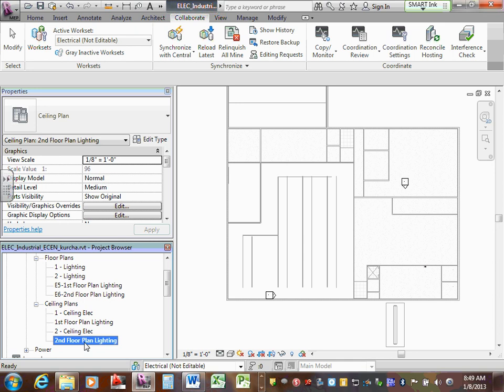Any questions, guys, about the E's, the drawings, E1 through E14? Piece of cake, we set them up. The next step was to set the views. We set up all the views that we need. The third part, guys, is now to set the drafting view. Remember the drafting view that we did? We're going to go grab a couple of drafting views.